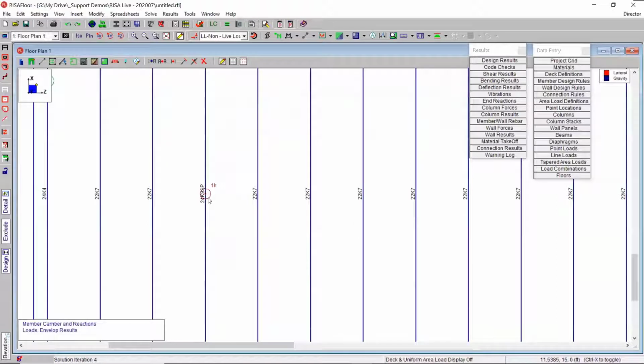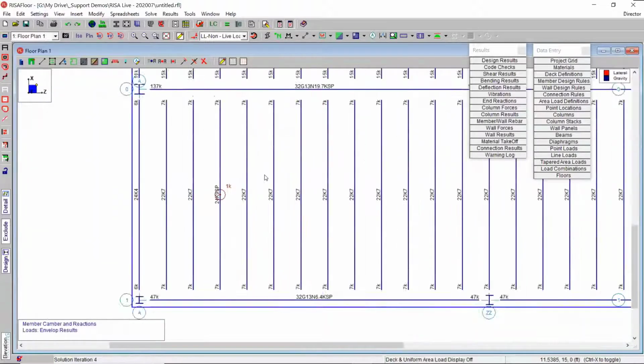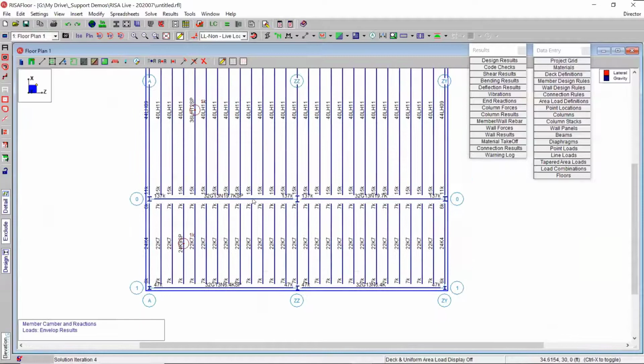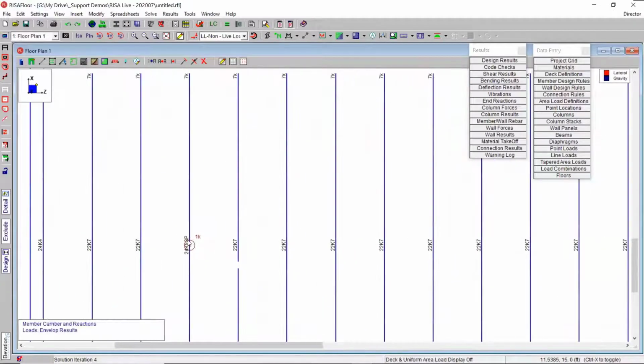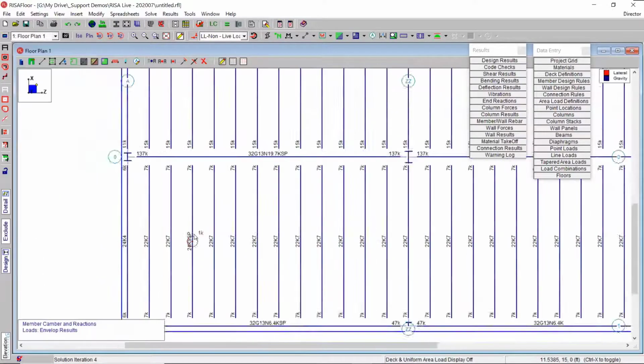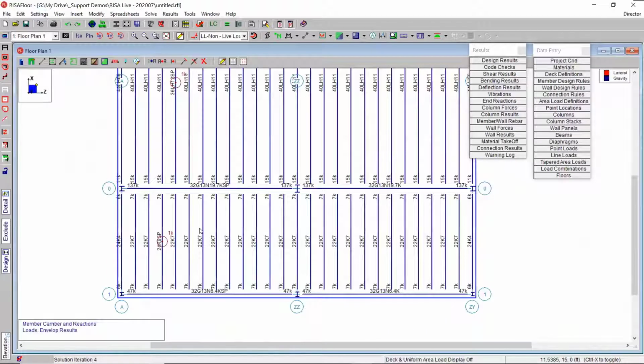The SP suffix is an indicator that these joists may need further detailing by the engineers or the SJI certified manufacturers to ensure adequate performance. So that's about the special joist. Just pay attention if you see these SP signs, you may need to pay some additional attention or requirements for this joist.